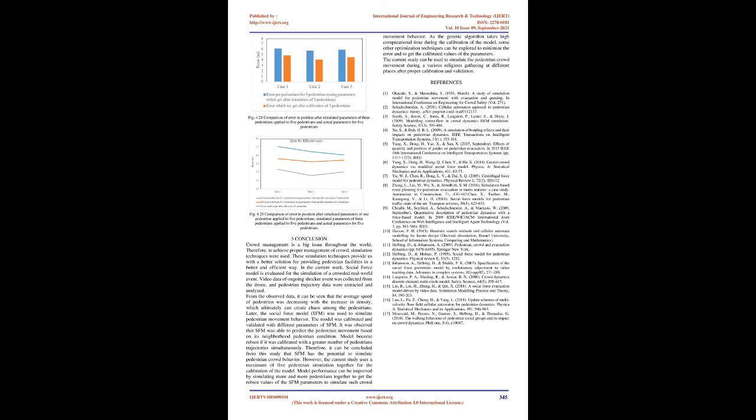Comparison of simulated and actual positions of pedestrians. From figures 4.22 to 4.24, it is observed that the error in position is significantly reduced if we apply the parameters which we get from a simulation of 3 to 5 pedestrians rather than applying the parameters which we get from a simulation of 1 pedestrian. As already discussed, if we choose more pedestrians for simulation, our parameters would work more effectively because they were calculated on the basis of all the pedestrians considered in the simulation.